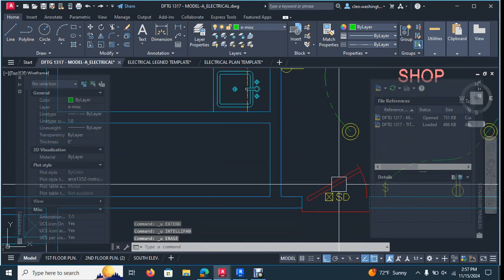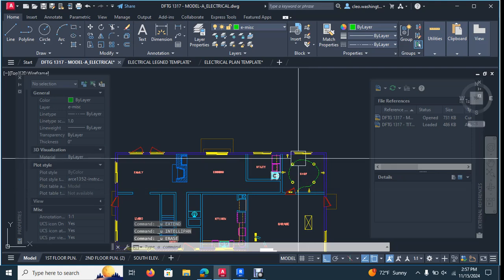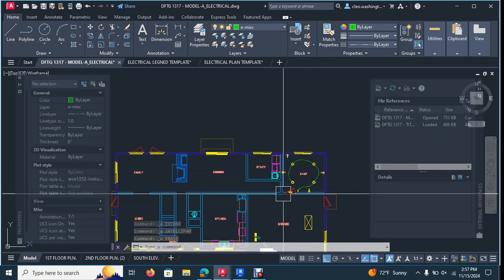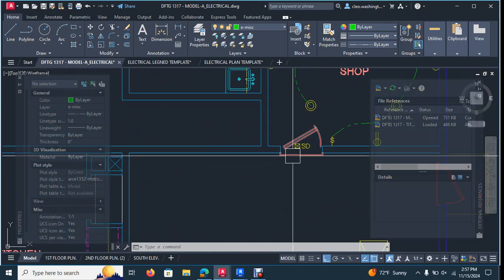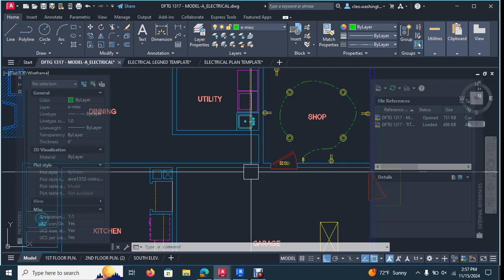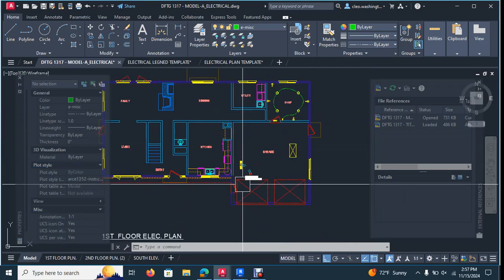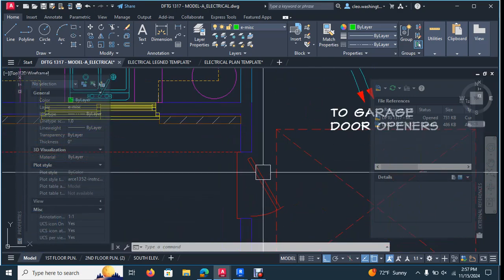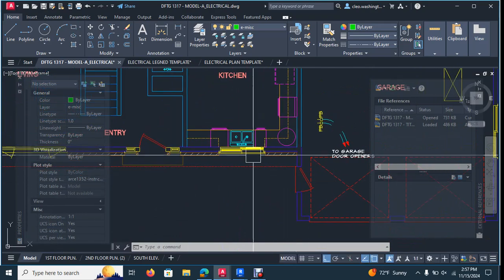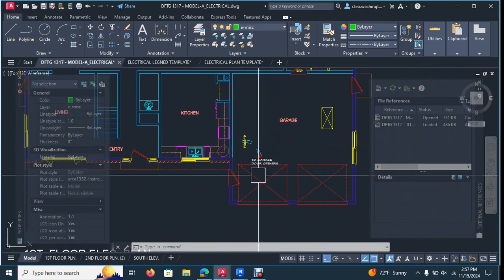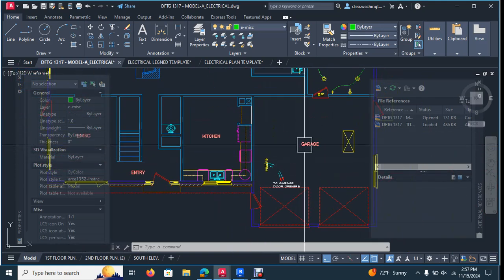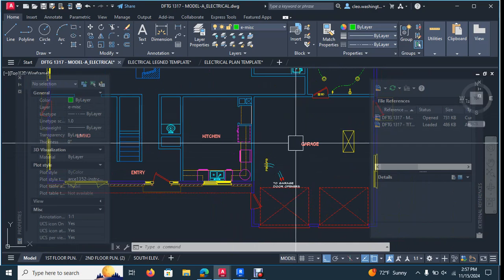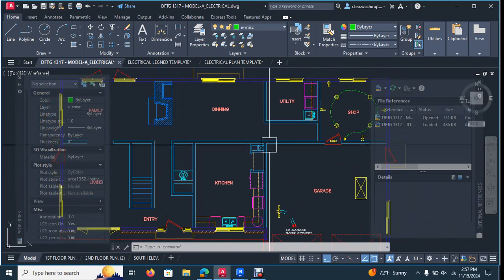Because it's some kind of shop. You could be in here spray painting something, right? And then you've got your dining room right here. So no, we're not gonna do that. What we're gonna do is add a door on this side that leads into the garage out of the house. The reason why I didn't pick up on it is because we had this guy, not noticing that it's basically coming from the exterior side. And that's cool, it's functional, we can do that, but I typically like to provide access to the garage from the interior spaces of the home or the residences, right?